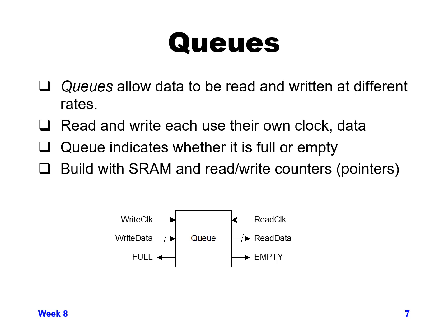You might have a burst write, for example, and you can only consume the values at a different rate. So you might write in like 20 values and then read them out over time. You know that the writes come in at a burst, and as long as you can read them out over a period of time and then another burst comes in, over time you average out and you're okay. But you might need to store the values so that you have time to consume them to do whatever calculations you need to do with them.